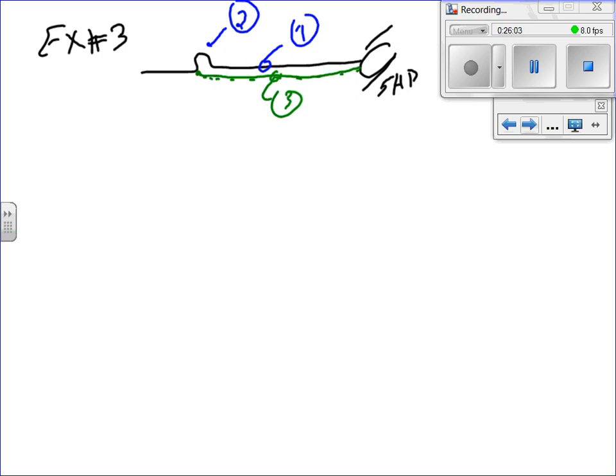I need the voltage. So for all practical reasons, let's throw a 240 volt on this motor. 240 single phase. This is a 240 single phase motor, and I need to size the conductor, and I need to size the equivalent grounding conductor, the overcurrent protection device. The overcurrent protection device, as it shows right now, is a circuit breaker. Circuit breaker, inverse type, 99% of the time, inverse type circuit breakers for this motor.